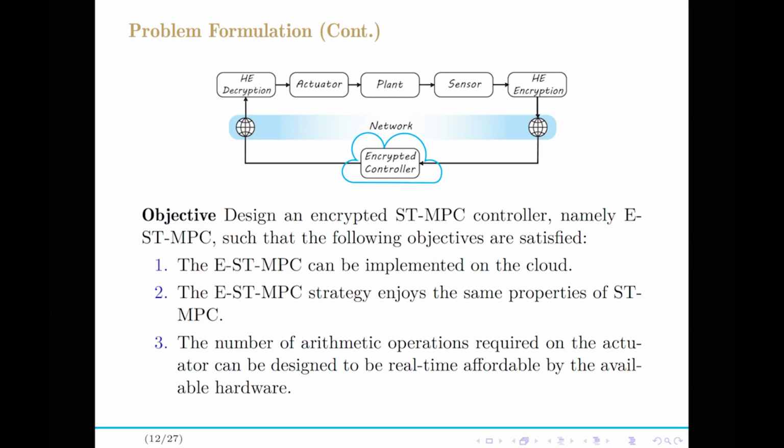So we're going to design an encrypted set-theoretic MPC with the following objectives. First of all, we want the controller to be implemented on the cloud. Second, we want this strategy to enjoy the same properties as set-theoretic MPC. And also, the number of arithmetic operations required to be performed on the actuator side should be designed to be real-time affordable by the available hardware.